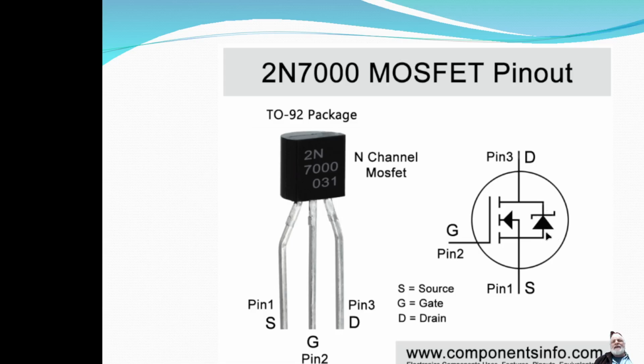So this diode is built into this MOSFET, and a lot of these power MOSFET devices and just power switching devices will have these diodes built in automatically. These diodes are there to allow the inductive load to discharge its stored energy without destroying the device. Because if you don't have a freewheeling diode and you have an inductive load, you can very quickly destroy that entire device, just the first time you use it and you dump that load.